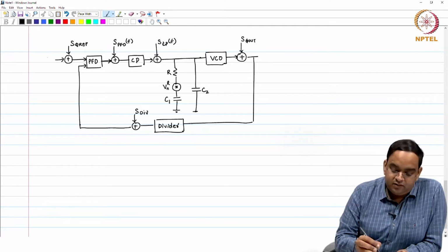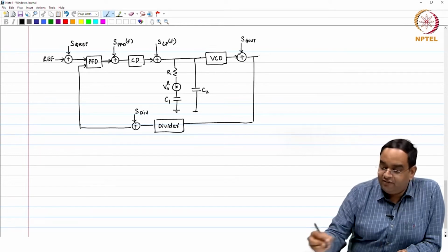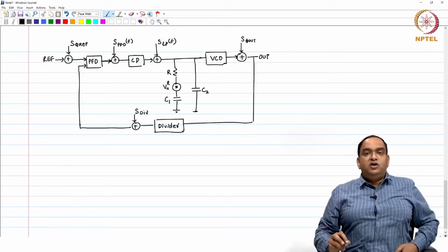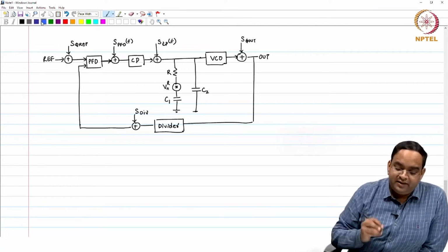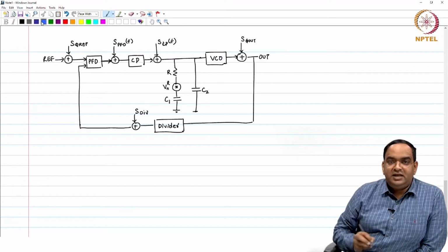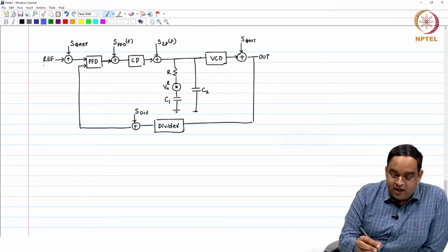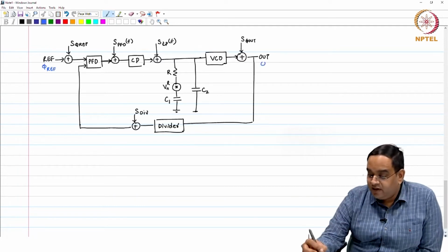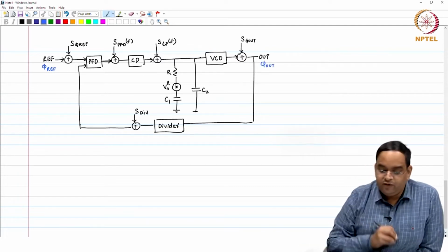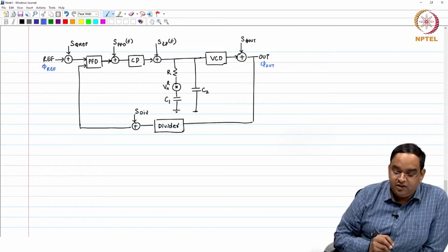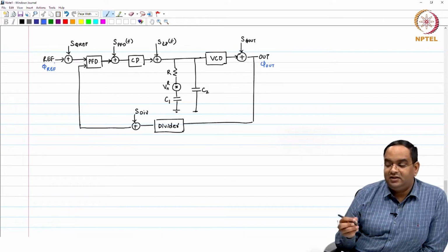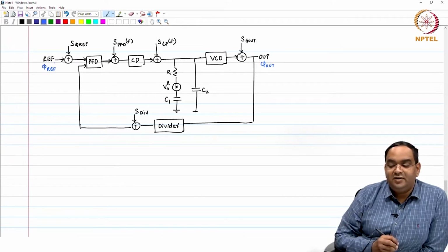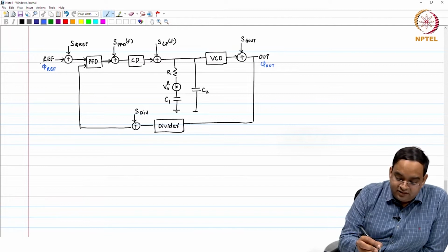Now, what I have done is just identify all the noise sources in the system. Now we do one more thing. In the case of a PLL, we are making sure that the output phase is locked with the input phase, or reference phase. So the variables we are looking at, other than the voltage or current signals at the input and output of the PLL, are phases.